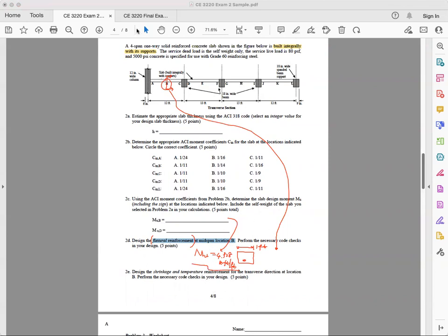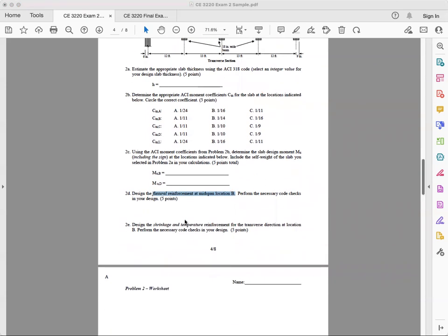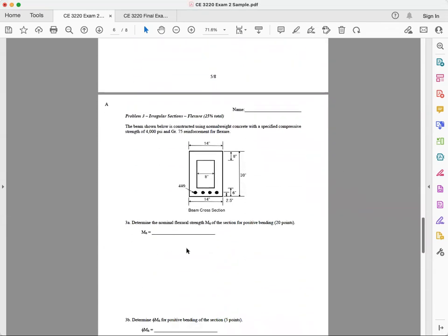All right. So moving on, after I did the longitudinal reinforcement, the problem is asking me to do the transverse direction shrinkage temperature. So how do I do shrinkage temperature? Remember, there's a maximum spacing, and there's equivalently a minimum amount of reinforcement to put in the section, right? There's a 0.0018, 0.0012 of Ag, where Ag is the cross-section area. Again, this is not so bad. You can go back to the lecture notes and find out, okay? All right, so that's problem 2, okay?